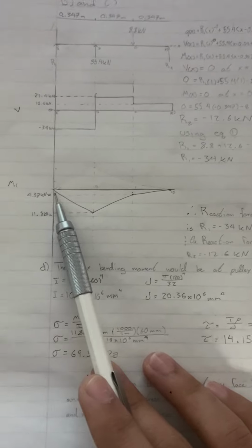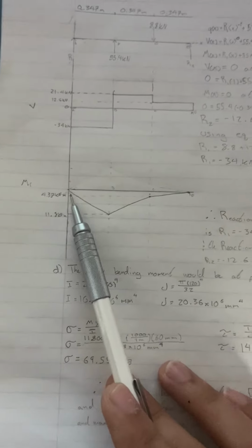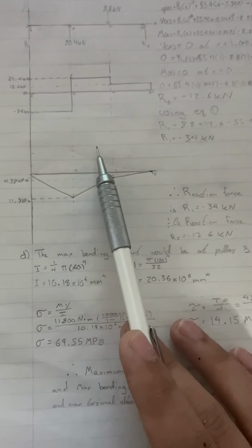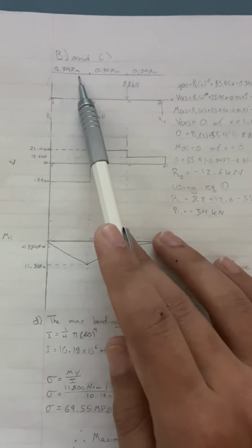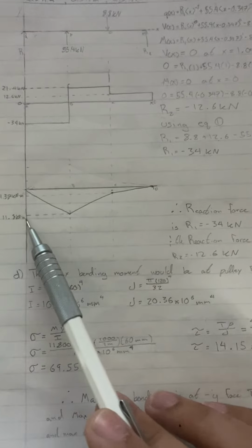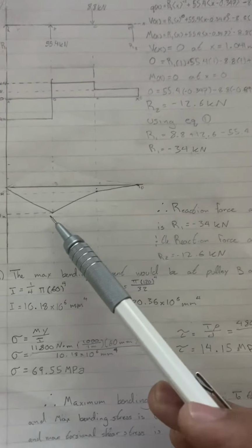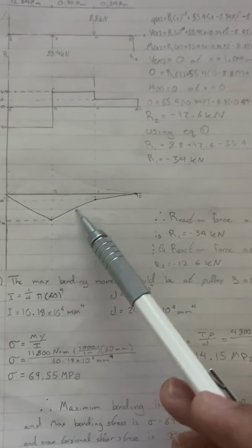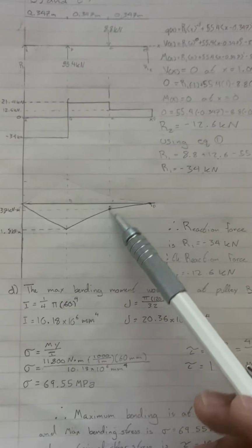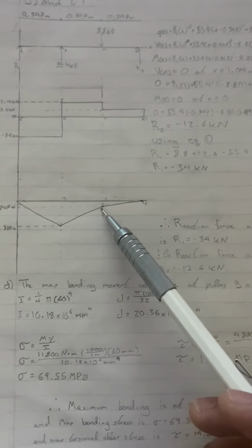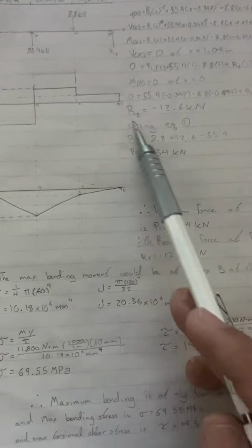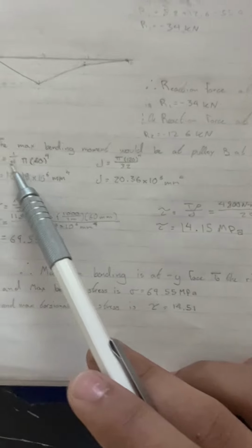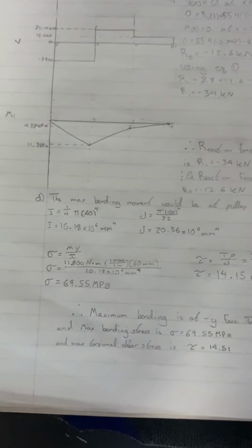Here in my moment graph, it starts off at 0 and goes down to 11.8 kilonewton meters, which is the initial force times the distance of 0.347 meters. Then turning terms on and off in the singularity function, I find that the second point of interest, at point C, which is the 8.8 kilonewton force, is 4.37 kilonewton meters, and then it reaches 0 as the last part of the singularity function is turned on, which is the 8.8 kilonewton force. And that is parts B and C altogether.